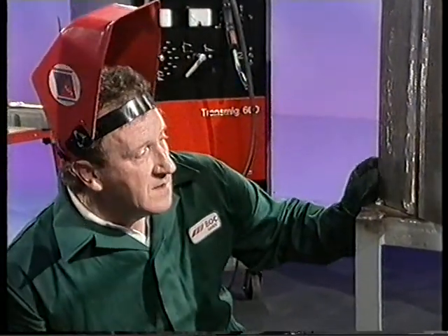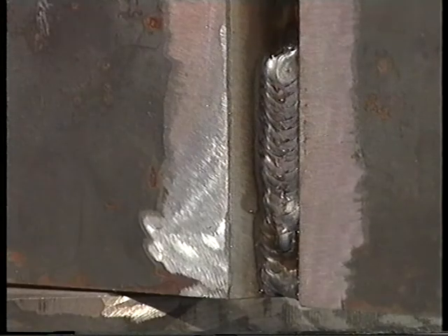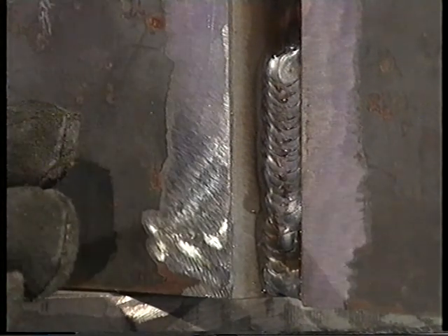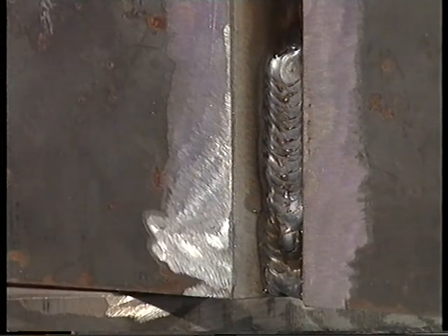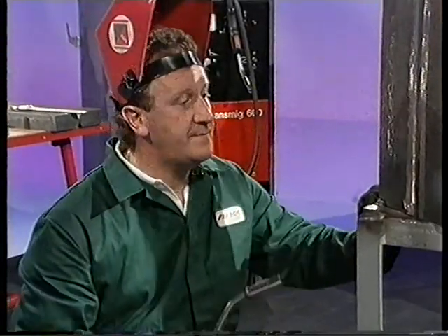Right. Okay. Excellent. Hope you can see, reasonably flat, not too much need for dressing afterwards. We'll go through the inter-run cleaning again, scrape that silicate off, wire brush the surface, grind the lump off, and fill up. Okay, Mel, that's the crescent weave. Are there any others? Yes, there are.